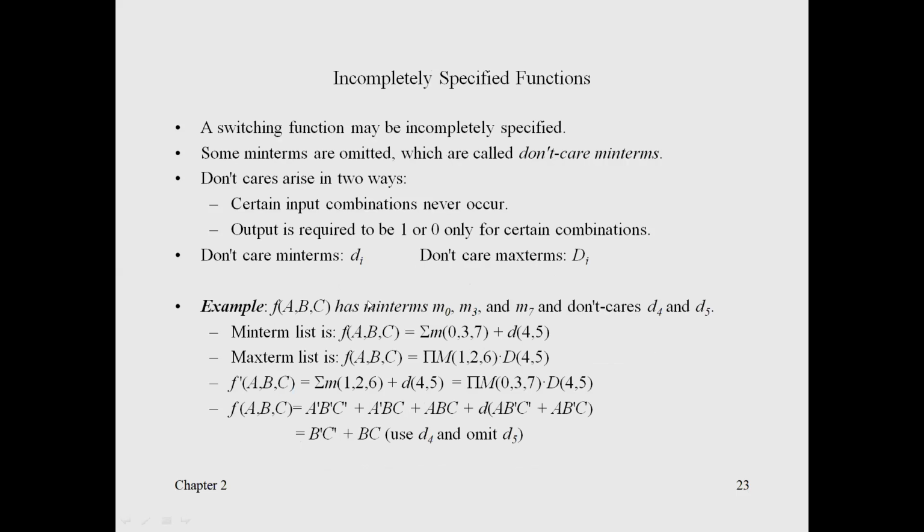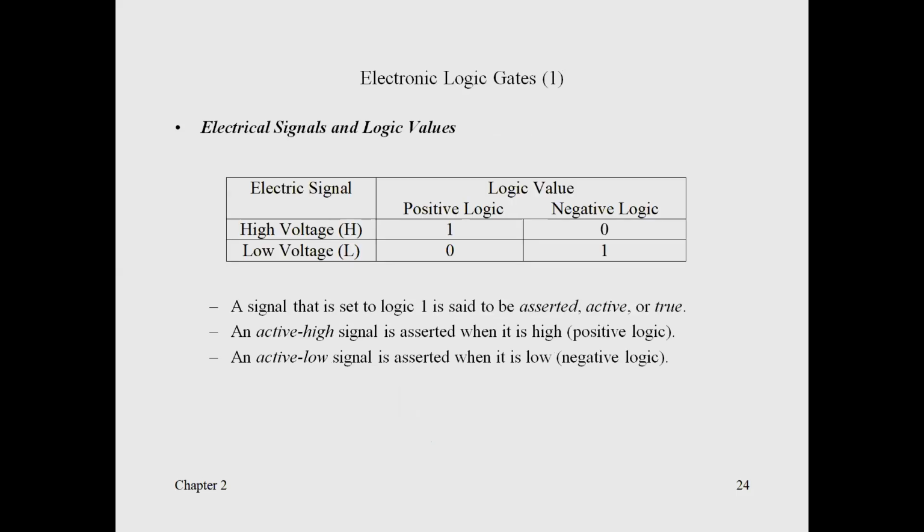Now these are the don't care conditions. Somewhere you will be given don't care conditions. In K-map we will study this at length, just to have an overview. If you have don't care terms, they will be given as D of 4, 5. When we take don't care terms, if they are of use, or if you have a further simplifying opportunity, then we take them, otherwise we don't take them at all. We will see later where and how we use them.